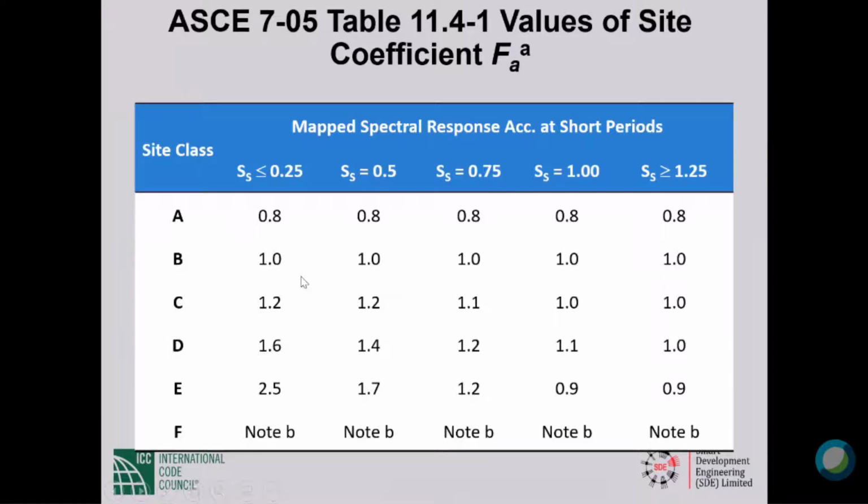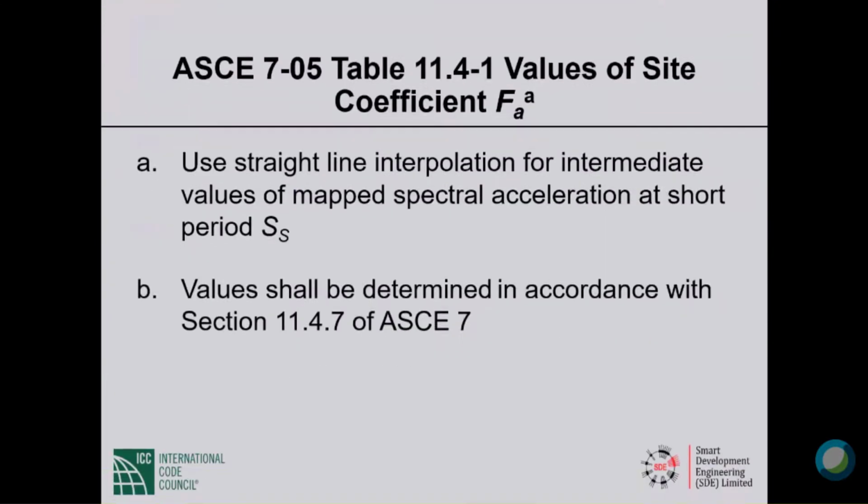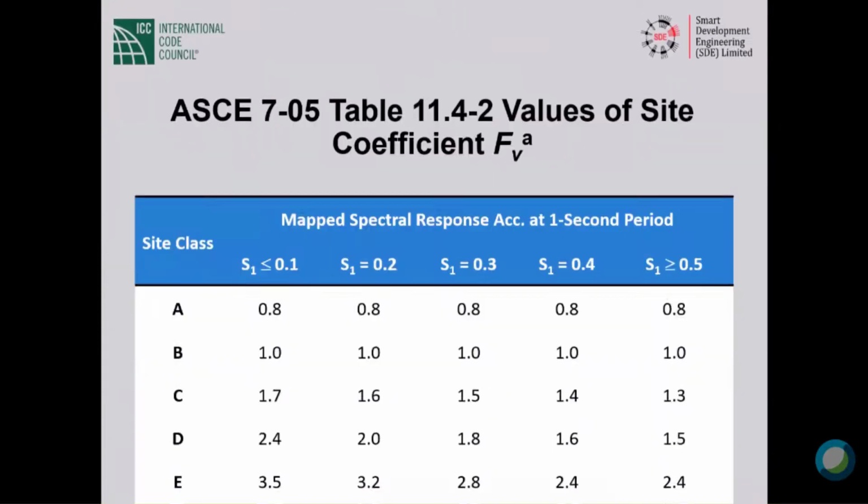Let me go to the next one. Okay, note B for site class F tells you that you need site specific analysis. You cannot use the spectrum of the code and site modification factors. These are details that I will let you read.